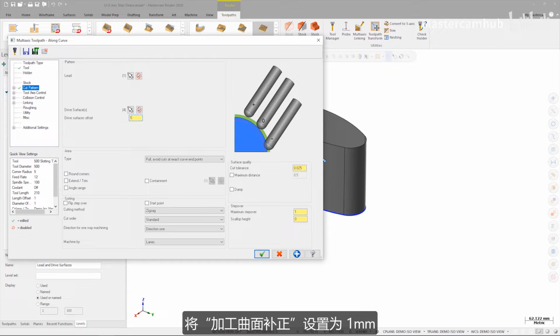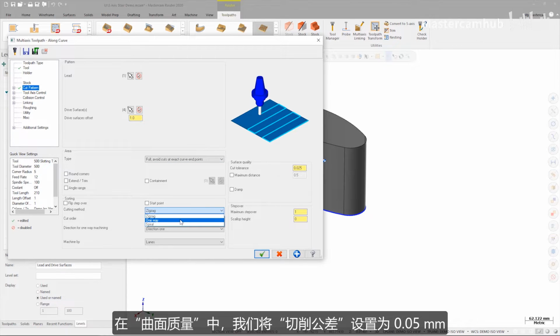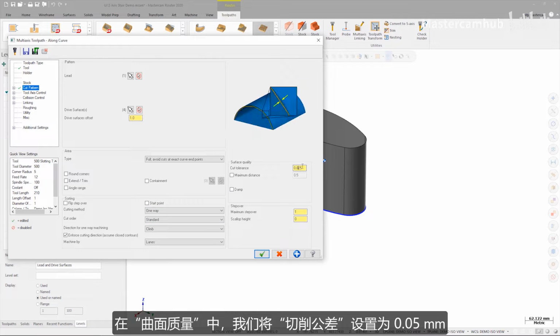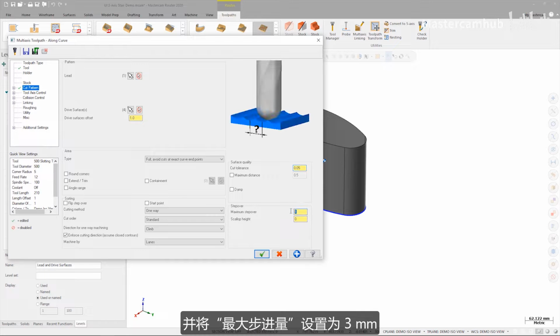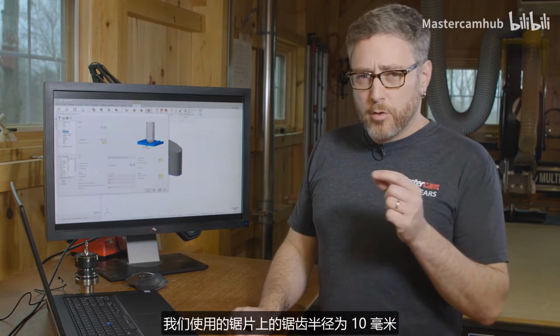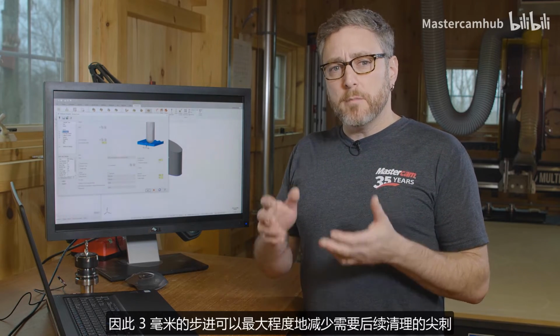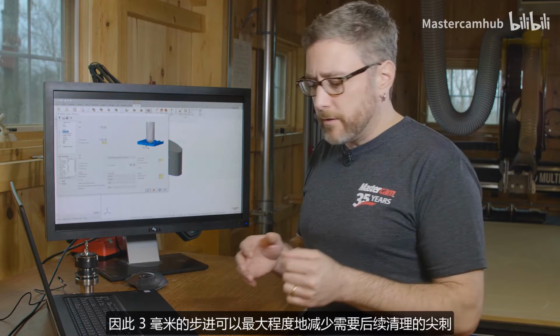Set the drive surface offset to 1 mm. In sorting, we'll set the cutting method to one way. In surface quality, we'll set the cut tolerance to 0.05 mm, and we'll set the maximum step over to 3 mm. The teeth on the saw we're using have a total radius of 10 mm, so a 3 mm step over is going to minimize the cusps that need to be cleaned up later.